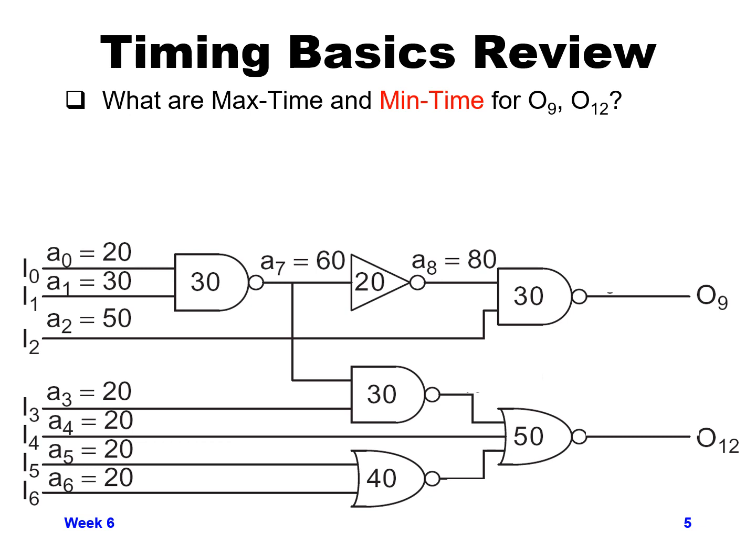and that has a 2-input NAND gate. One input is coming in at timing A7 of 60 picoseconds. The other one is coming from input I3, coming in at timing A3 of 20 picoseconds. So 60 and 20. 60 is the largest number, so we add that to the 30 picoseconds delay through the NAND gate, and we get an output of 60 plus 30 is 90 picoseconds for timing A10.